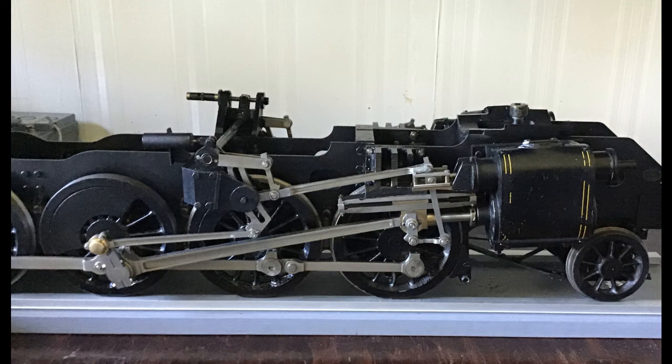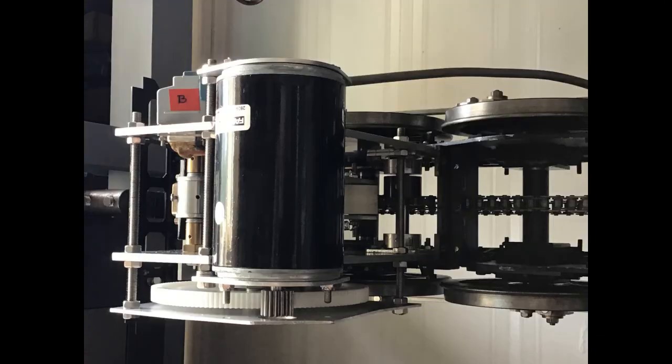However, on reflection, what I really wanted to do was to limit the load on the teeth of the single 140-tooth gear and the linkages. I was less interested in accurately controlling the loco pull via dB1. Nevertheless, I still did want the loco to make a reasonable contribution and not be a load for the tender. My solution was to operate both the tender and the loco under voltage control, but with these provisos.